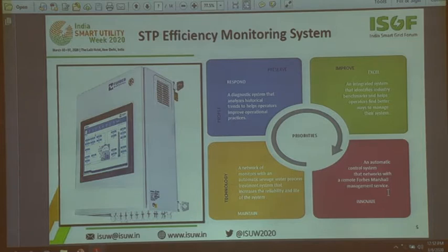Here, the technology will give you some alerts. It will start giving you some diagnostics. Based on those diagnostics, the people will start improving upon those processes. Earlier, if there is a PID loop, it will keep functioning, but it will now tell you how the loop has actually performed, whether your process value was close to your set value or far away from that. This will improve a bit from what we were doing with mere technology.